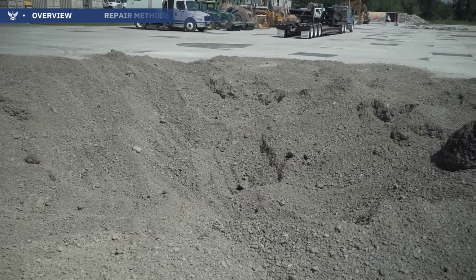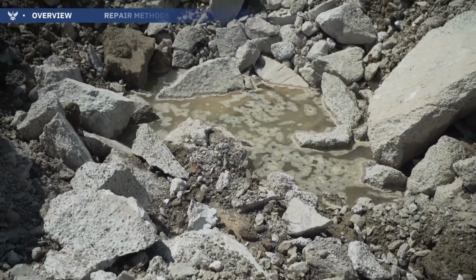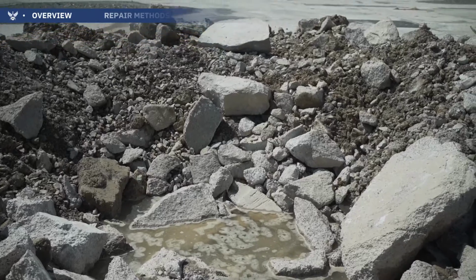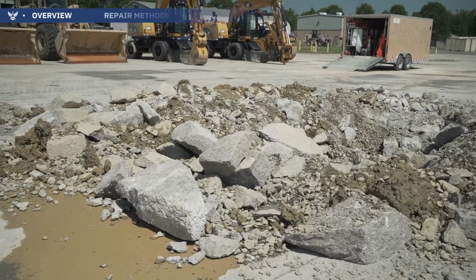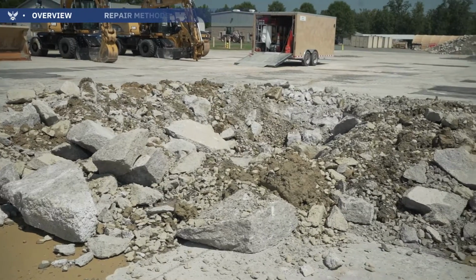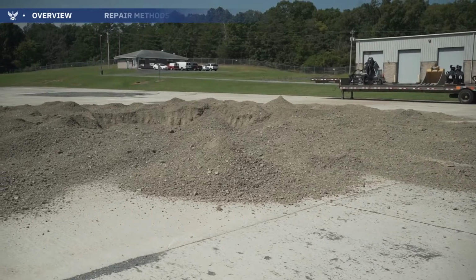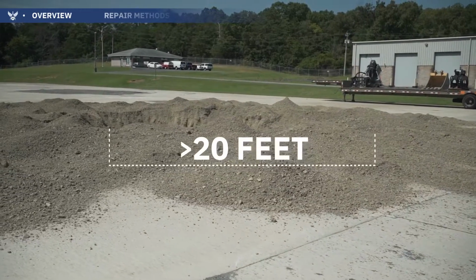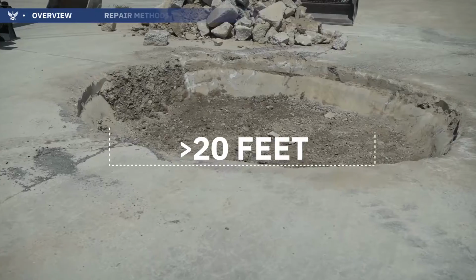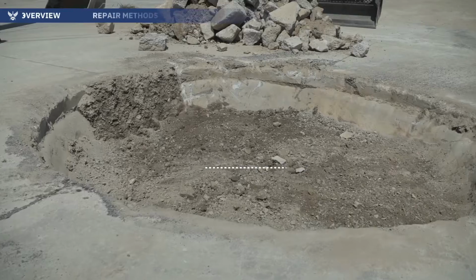Craters represent damage that penetrate through the pavement surface until the underlying base and subgrade soil, which uplifts the surrounding pavement and ejects base, sub-base soils, rock, and pavement debris around the impact area. Craters represent much more severe damage than spalls. Large craters have an apparent diameter equal to or greater than 20 feet. Small craters have an apparent diameter less than 20 feet.